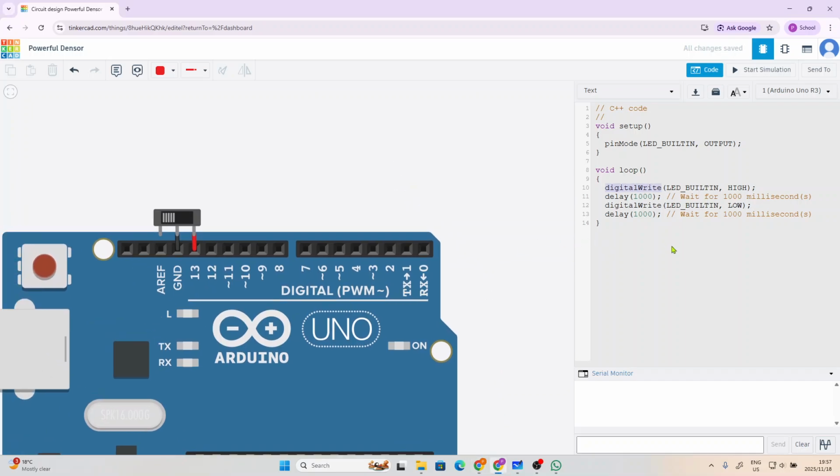Can you explain what Kat just said in study terms? Okay. When the Arduino is set to an output pin, we have two kinds of write. You see this write function here. We have digital write and analog write. The difference is digital can either be on or off, and when it's on, it will go at max voltage, which in this case is around 5 volts, I believe.